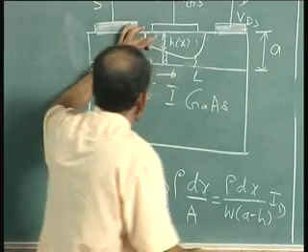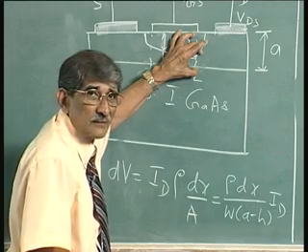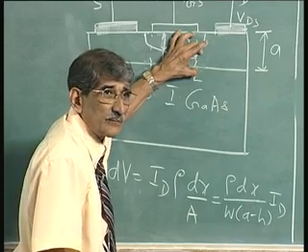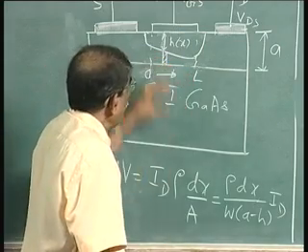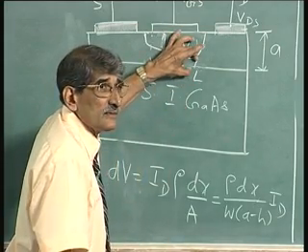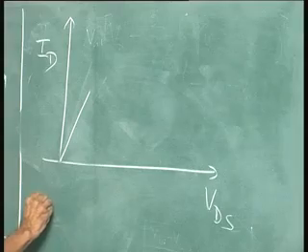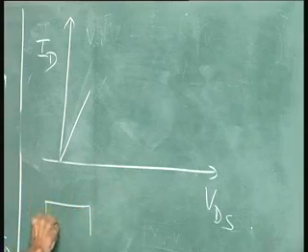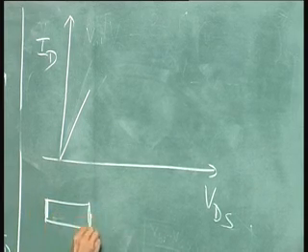the resistance, which was having the same area, is no longer maintained. The area is not maintained constant; the area keeps on falling. How much the area keeps on falling depends upon how much VDS is. So, you can see you have a resistor now. Originally you had a resistor like this with the contact like this.